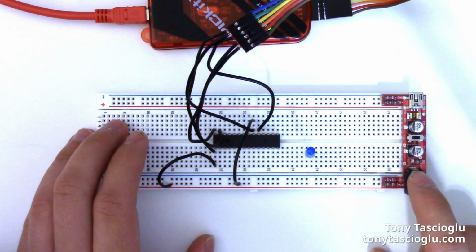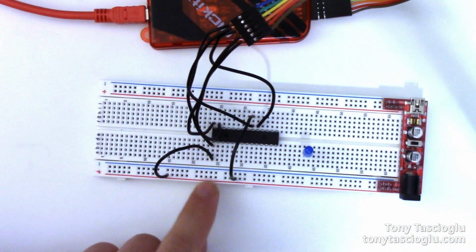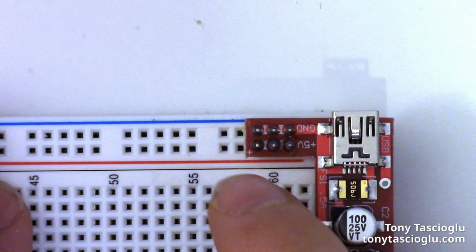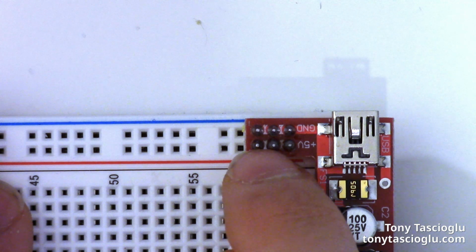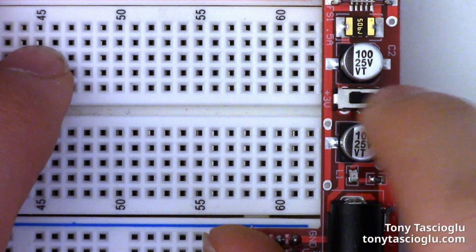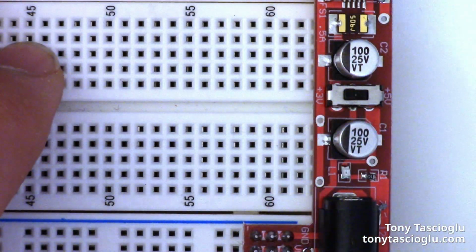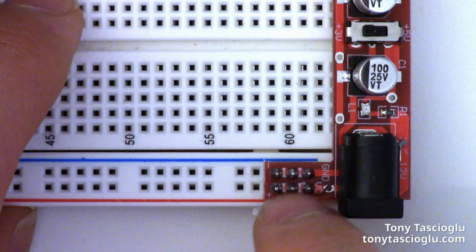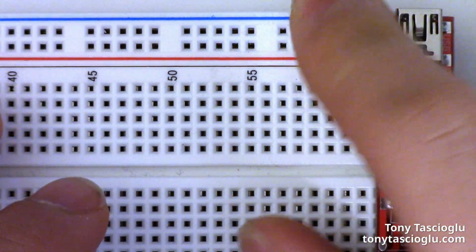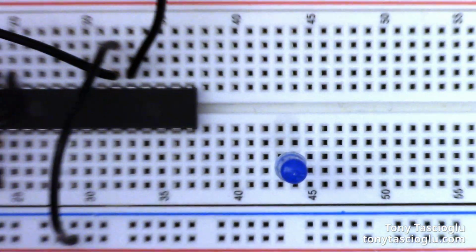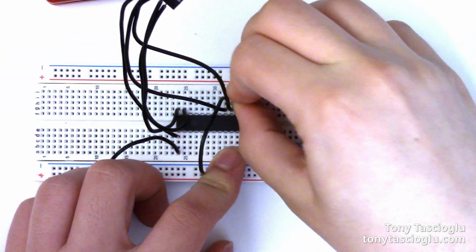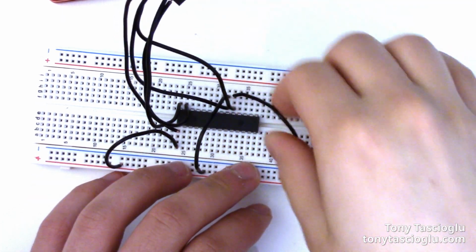If you're using one of these breadboard power modules, please be careful to connect it to the correct rail. Because if I zoom in here, you will see that the top rail is always connected to ground at 5 volts, but it connects the bottom rail of your breadboard to ground and VCC, where the VCC voltage is selectable by this slider. Make sure you don't accidentally fry any of your components. Unlike other breadboard power modules, which always synchronize the voltage across them, this one does not. So it's just something to be cautious of if you're using this particular model. Now the grounds on any circuit are connected, so which ground connection you use doesn't actually matter.